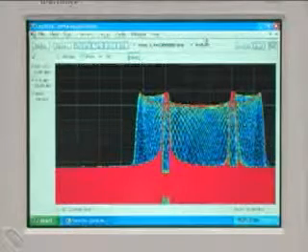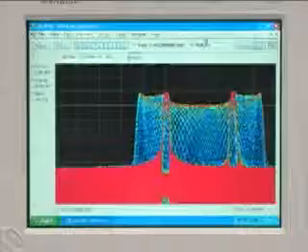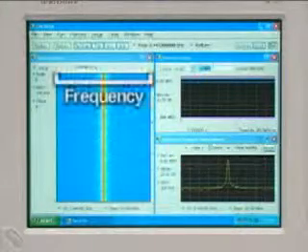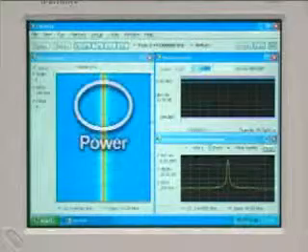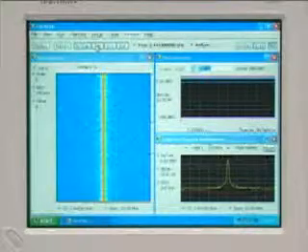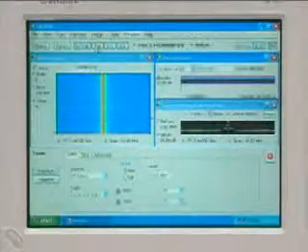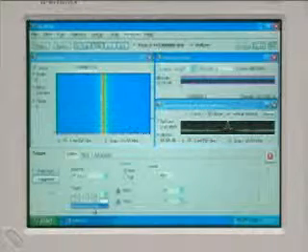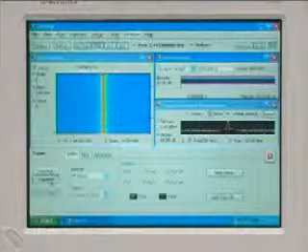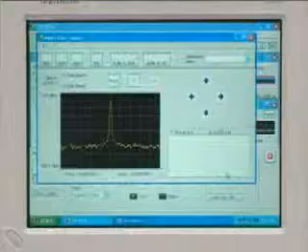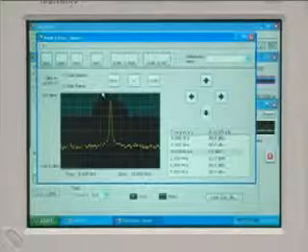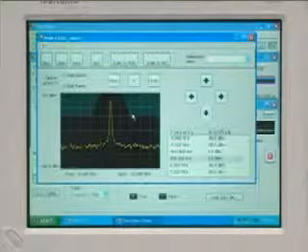So, in switching over to spectrogram, which will show frequency changes over time, with time on the vertical, frequency on the horizontal, and color indicating power intensity, we can also increase our analysis length in the time overview window to 900 microseconds duration, anticipating that that might be a likely length of the transient event. Then, using the Tektronix patented frequency mask trigger, we can selectively trigger on that glitch.